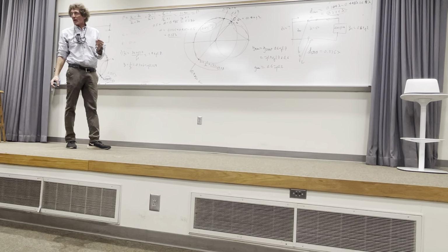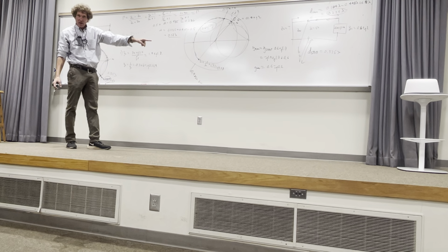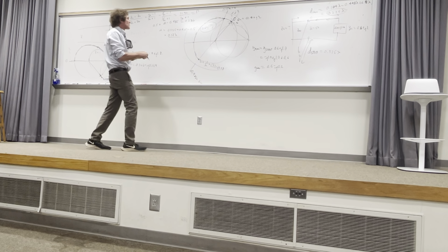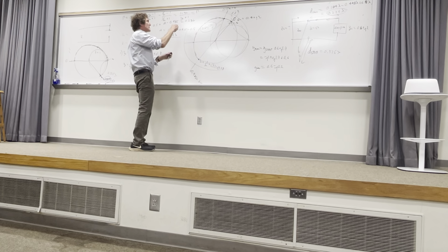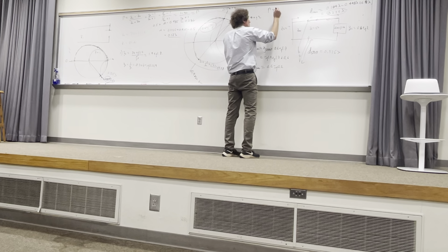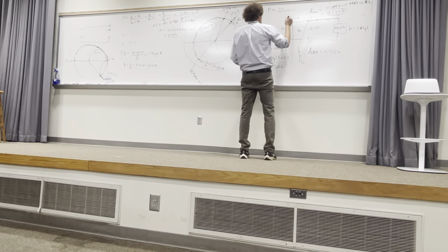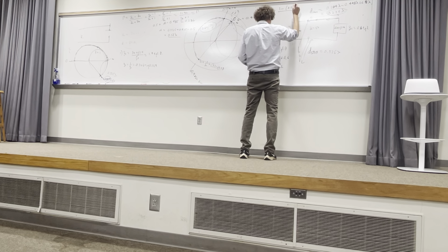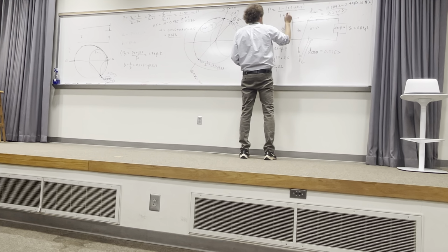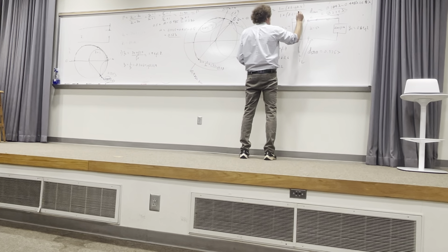Yeah, that's right. All right, now, if that's 1 minus YL over YL plus 1, you've got the value of YL right there, that Y new. Y'all follow me? I'm calling it L, but it's really Y at the point where it's connected, so the Y new. So now the reflection coefficient would be equal to 1 minus this value, which is 0.6 minus J 0.2, over 1 plus that value, 0.6 minus J 0.2.